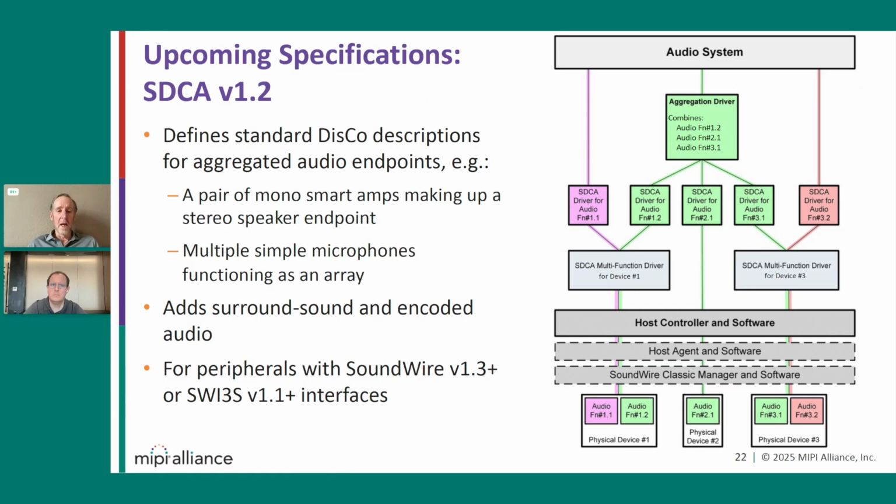We're also looking at better support for desktops. There is a function type called retaskable jack that provides the ability to have these 3, 6, or more 3.5 millimeter jacks that can be used in various ways, such as having a microphone input and line input, or changing those to actual outputs so you could support multi-channel audio. And so we're providing that capability.